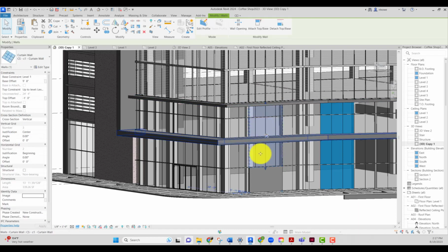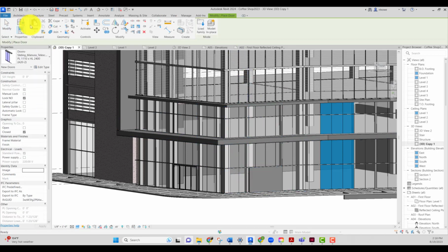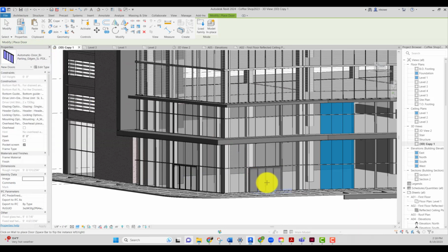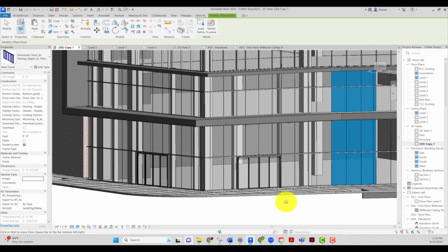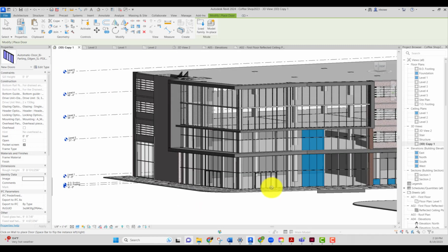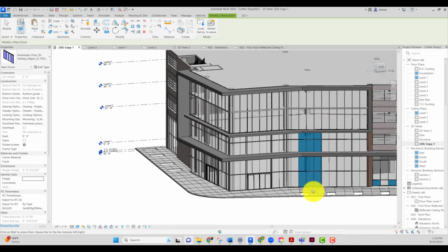So this one starts at 9'8", and then I made a generic wall using the I1, put in a basic wall that went up to 9'8", and then I'm just going to now place a door, place this Gilligan door inside of that. Seems like a bit of work, but not too bad actually. So that's what I did for these 2 doors. So just kind of note that. I thought it was something a little bit specific about this project as opposed to normal projects.